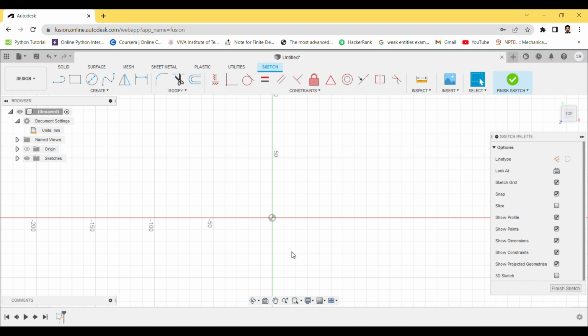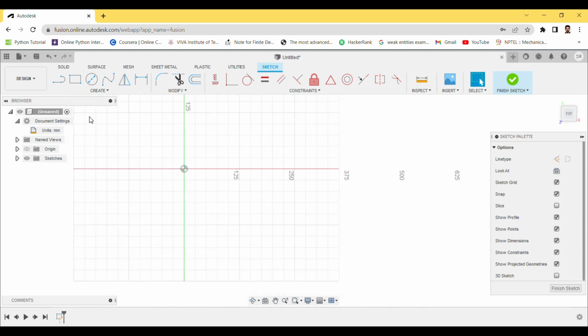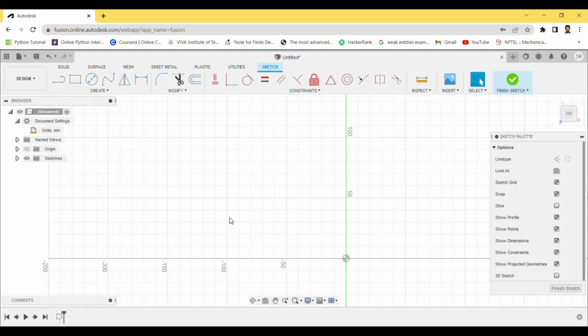Now the job that I'm going to draw or design, whatever drawing I have at my reference end, it is in the second quadrant. So I'll start drawing it. I've selected the line option from here. I will click over here randomly, and afterwards I will give the unit. Now I will select a straight line. The distance of it is 100.